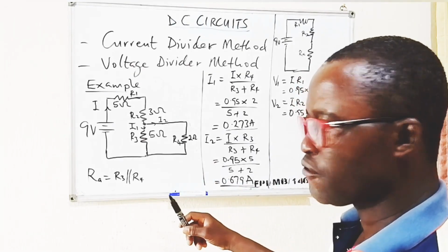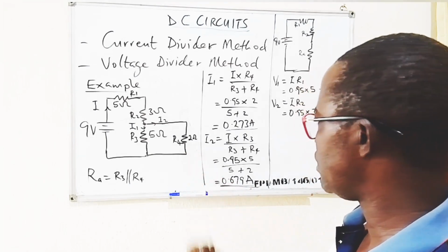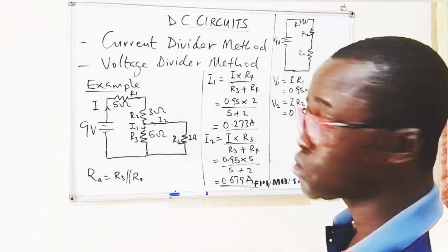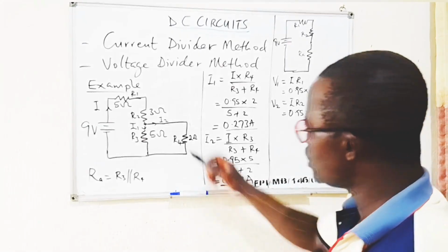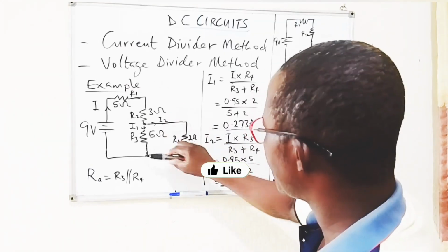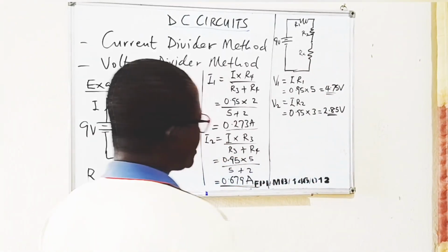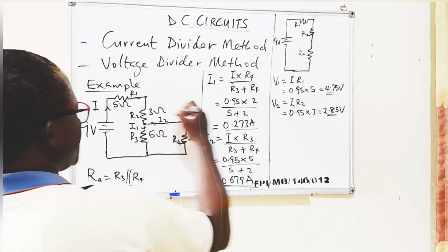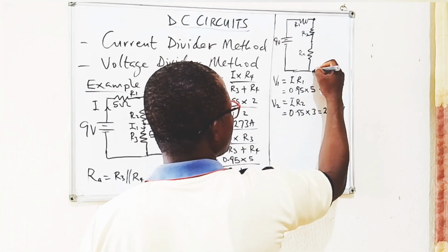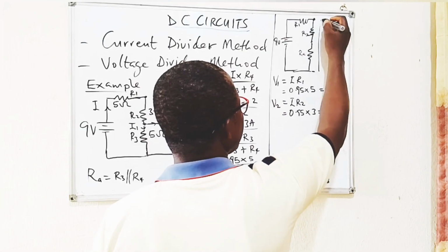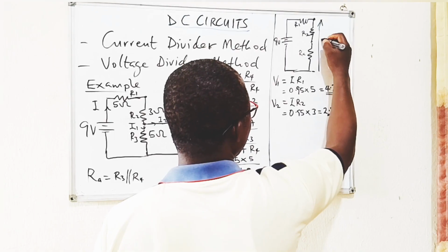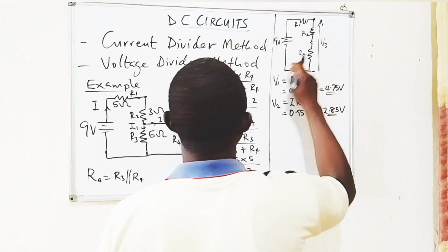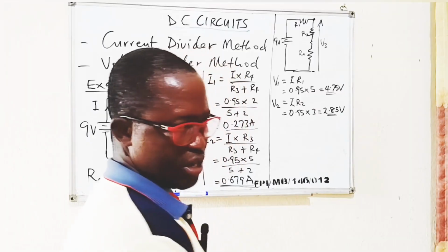All right, now we are left to determine the voltage drop across R3 and R4. Fortunately for us, since these two branches are in parallel, there will be the same voltage drop across both of them, across the combination of the two. So we need to determine only one voltage drop here. And that we can get by splitting the voltage from this point to the ground between R2 and RA, which we can call V3, using the voltage divider method.